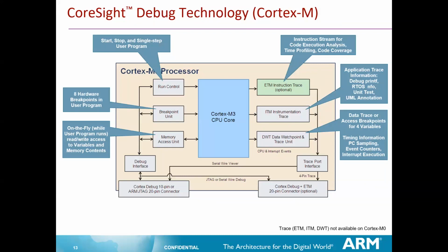But dedicating a UART just for this printf information, which is just a traditional debugging way, putting some statements inside the printf just to ensure the processor is executing in a flow, just for sending this debug related information, you're dedicating a UART continuously.